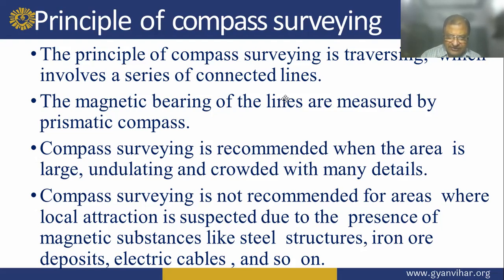And compass surveying is not recommended for areas where local attraction is expected due to the presence of magnetic substances like steel structures, iron deposits, electric cables, and so on.